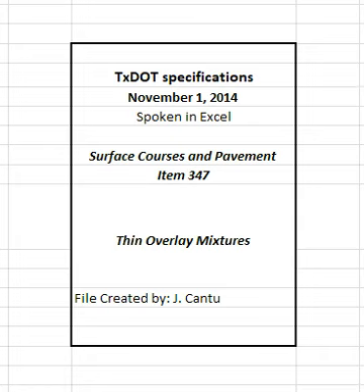4.7.1 Weather conditions. 4.7.1.1 When using a thermal imaging system, the contractor may pave any time the roadway is dry and the roadway surface temperature is at least 32 degrees Fahrenheit. However, the engineer may restrict the contractor from paving surface mixtures if the ambient temperature is likely to drop below 32 degrees Fahrenheit within 12 HR of paving. Provide output data from the thermal imaging system to demonstrate to the engineer that no recurring severe thermal segregation exists in accordance with Section 347.4.7.3.1.2, Thermal Imaging System.